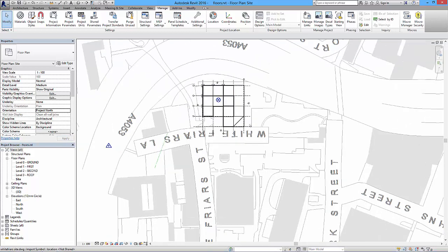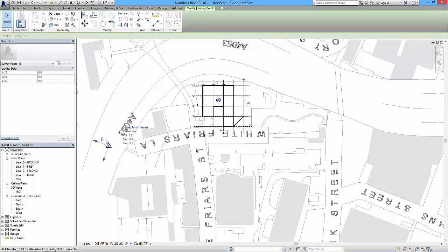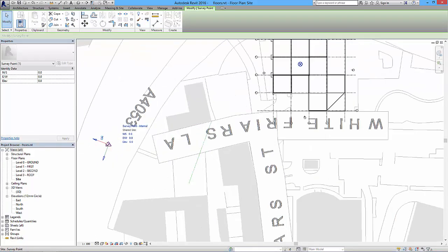The only thing that's left for us to do now is to relocate these markers. So this one is going at the corner of our project. Some corner, doesn't matter which one, but I'll put it on this back corner there. And this one is going to come and move to that position there. So I'll select this first. You've got to unpin it, and then we can move it. Keep forgetting that if I just click inside it, it's not going to do anything. So I've now snapped that to that point, and I can unset it.